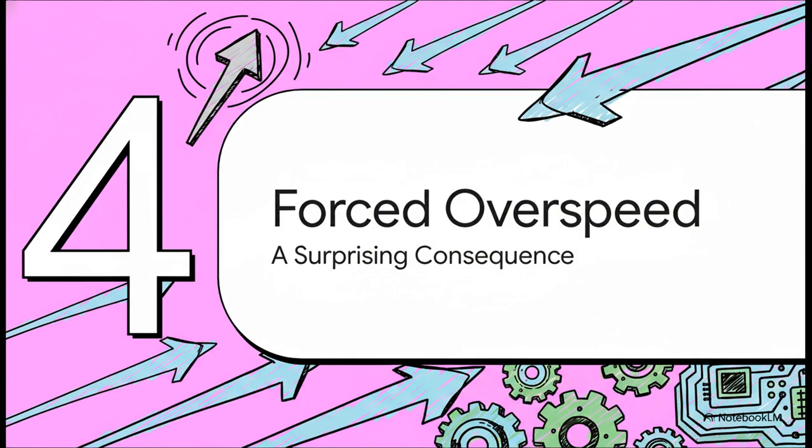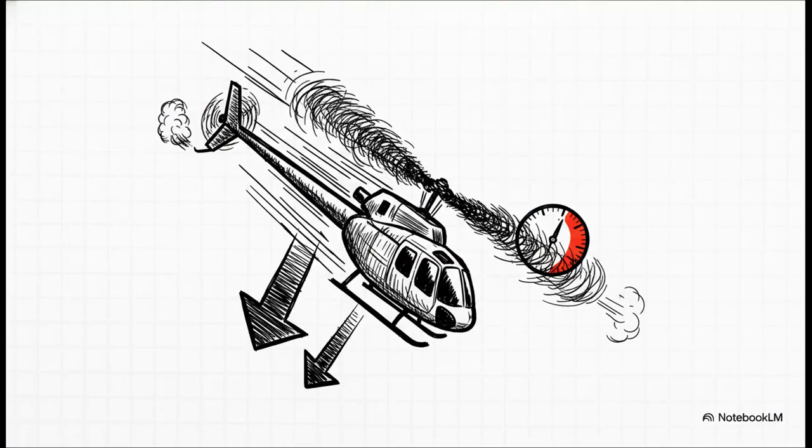This unique logic has one more surprise in store, a totally counterintuitive consequence that shows up during high-speed flight, a phenomenon they call forced overspeed. So, let's set the scene. The helicopter is in a fast dive. Air is rushing up through the rotor, spinning it way, way faster than the governor's target speed.